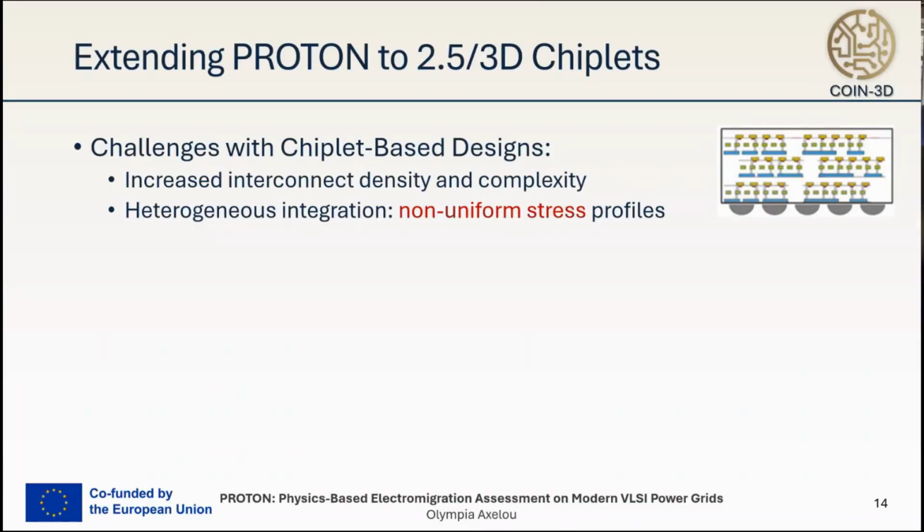And now, in order to conclude my presentation, let us take a step forward and think about chiplet-based designs. Chiplets bring unique challenges to electromigration analysis. The increased interconnect density and complexity can significantly impact reliability. And when introducing heterogeneous integration, we are faced with non-uniform stress profiles that are tough to predict. These issues are amplified for vertical interconnects like TSVs and microbumps that create stress hotspots.